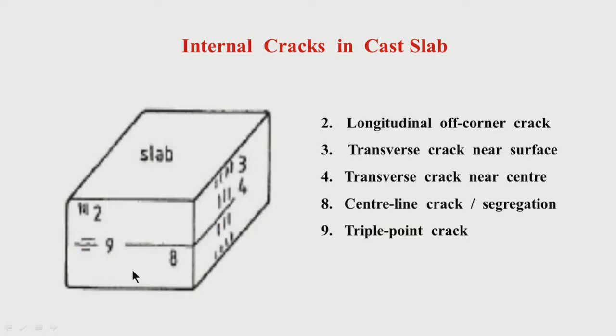Even if you take precautions during normal casting, such as low superheat, less phosphorus, less sulfur, and a high ratio of manganese to sulfur, you can have less intensity of segregation and crack formation at the center. Nevertheless, you will always have some amount of segregation and some shrinkage crack at the center.